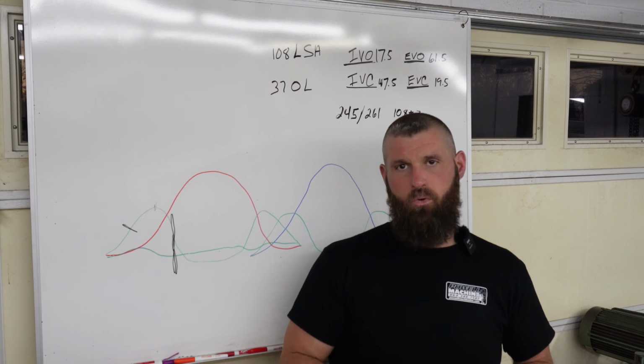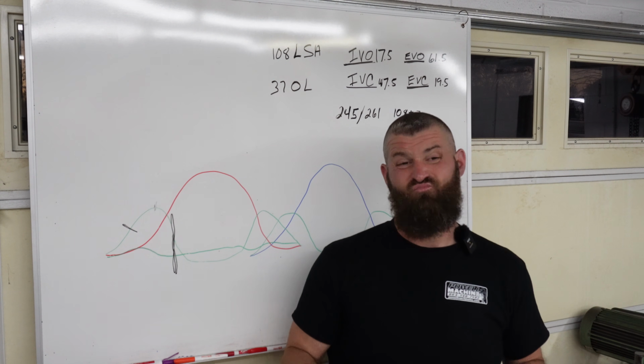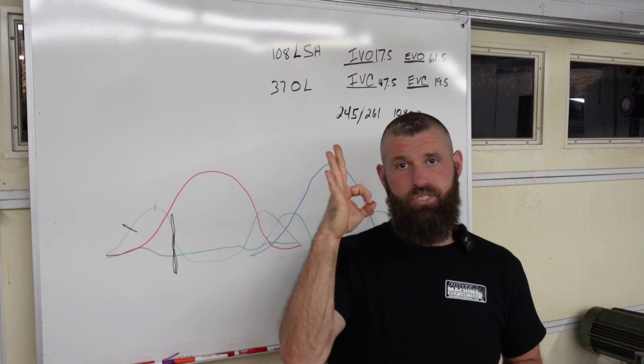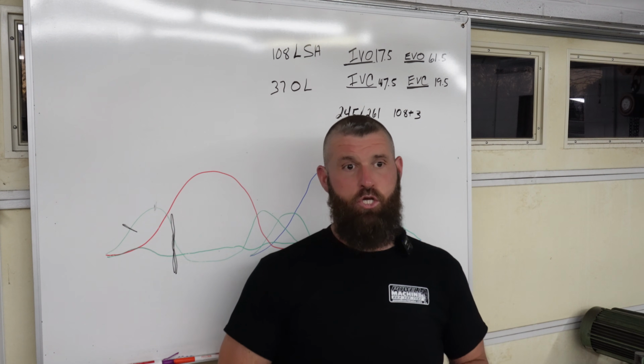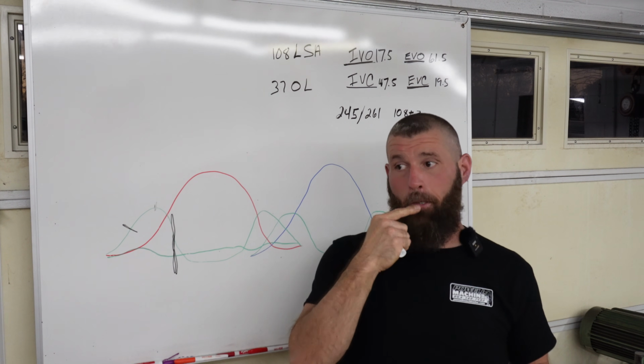Average horsepower and torque wins races, period. So if you're focusing on peak, you're just out to lunch, because peak means zero. It just doesn't mean anything. Look at the averages, figure out what your RPM window is, right?